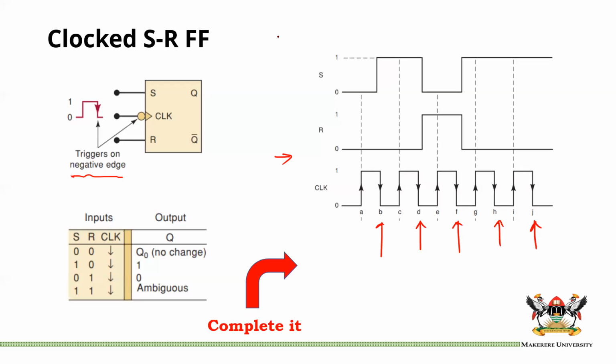Usually I'll give you a flip-flop with, actually, before I was interrupted, Kichoncho had asked a very interesting and very important question. I'll say in the question whether it is an NGT or a PGT. If I don't, you will see either the bubble or no bubble. If it is a bubble, you know it's NGT. If it is no bubble, you know it's PGT. So this is an NGT. If it was a PGT, it would look like that.